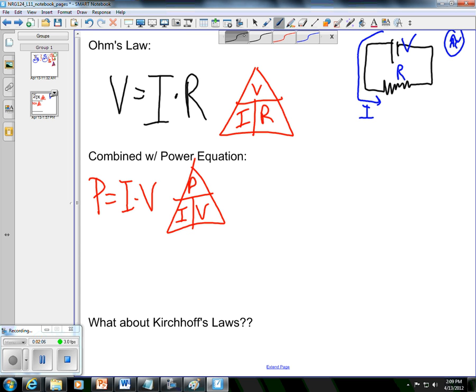We can substitute the Ohm's law equations into the power equation, the pi equation. And we can get a couple other useful equations. The whole reason for reorganizing these is if we don't have certain values. So let's say that we didn't have the voltage, but we wanted to find power. So voltage is current times resistance. Well, that's Ohm's law. That's the basics. I don't even need to rewrite that, right?